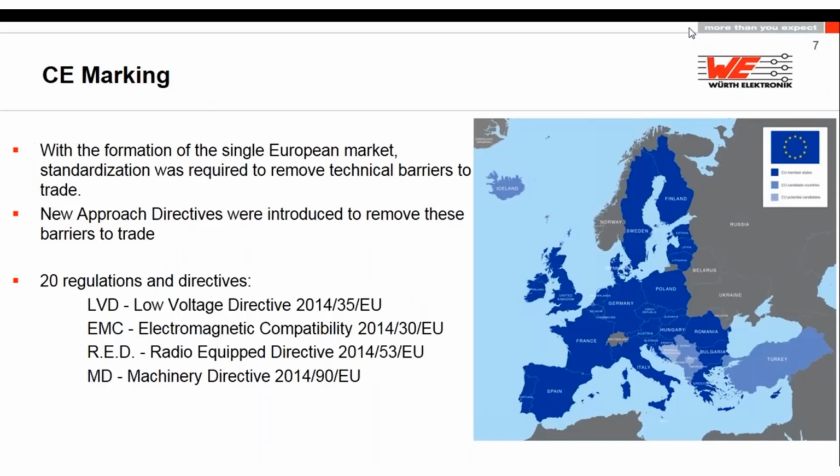First of all, when you are talking about EMC, you have to fulfill some different directives. When you put something on the European market and you want to sell this device, it must be compliant with CE compliance. And the CE marking is different depending on your device. If it's a low voltage device, or you have a radio module inside, an RF module which communicates, in the RED the EMC compliance is already automatically inside.